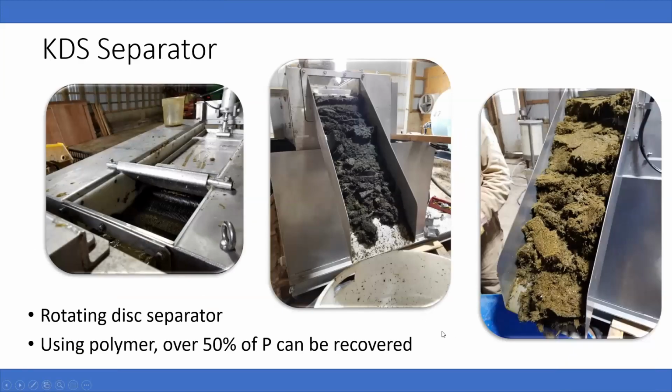So it takes several steps. You can't just take a pit of raw manure and add acid and then add lime. It doesn't work quite like that. First and foremost, you need to screen out a lot of the big solids. So when you're thinking swine manure, the hair and the grit and everything that's in the pit, you need to screen that out.